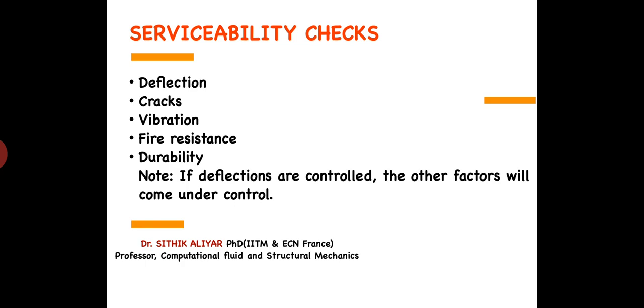We are going to design the structure as an under-reinforced section, and an under-reinforced section always has ductile behavior. So there will be a deflection when the load is applied. Up to how much deflection we can allow, that is the first check we will do. The second check is crack.